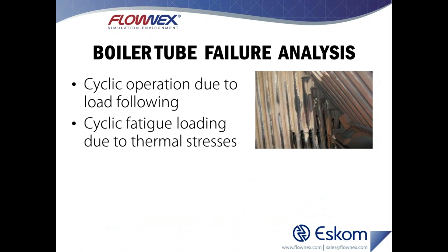So these coal-fired boilers have to change their load to follow the demand from the public. And as a result, these units have to go through these cyclic loading patterns. And this results in some rather large thermal stresses inside of the system and often leads to these boiler tube failures. So a tube failure is commonly just a small little hole that results in the side of one of these tubes and basically results in a loss of pressure in the system and a unit trip. This then results in quite a large amount of downtime and costs the company a lot of money.